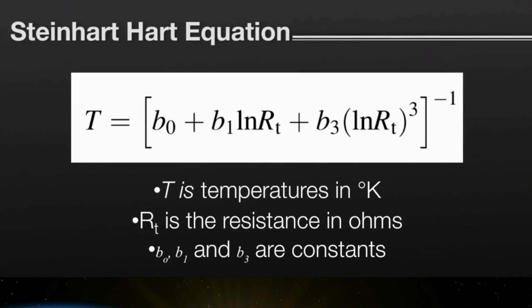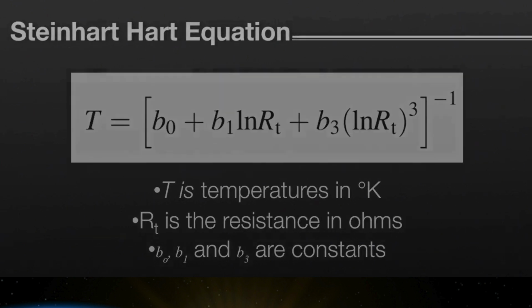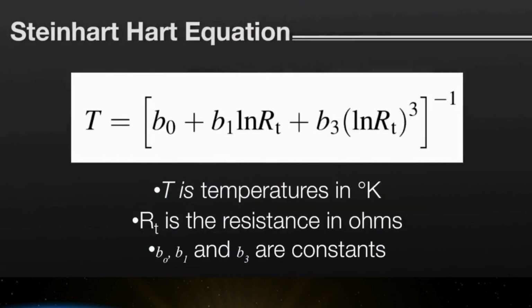The Steinhart-Hart equation models the highly nonlinear behavior of thermistors. These guys were geophysicists who published their research findings for thermistors back in 1968. And when you're the first guys to publish an equation or a physical constant, they usually get named after you. The logarithmic terms in the equation and the inverse relation of the terms to temperature do two things. They explain the large fall-off in resistance over a narrow temperature range, and they make for a very smooth-shaped curve.